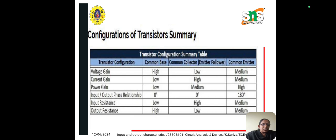So this is the table which represents the summary of different transistor configurations. So common base, common collector and common emitter. Common collector is also known as emitter follower. So the voltage gain is high for common base, it is low for common collector and medium for common emitter. Current gain is low for common base, high for common collector and medium for common emitter. Power gain is low for common base, medium for common collector and high for common emitter.